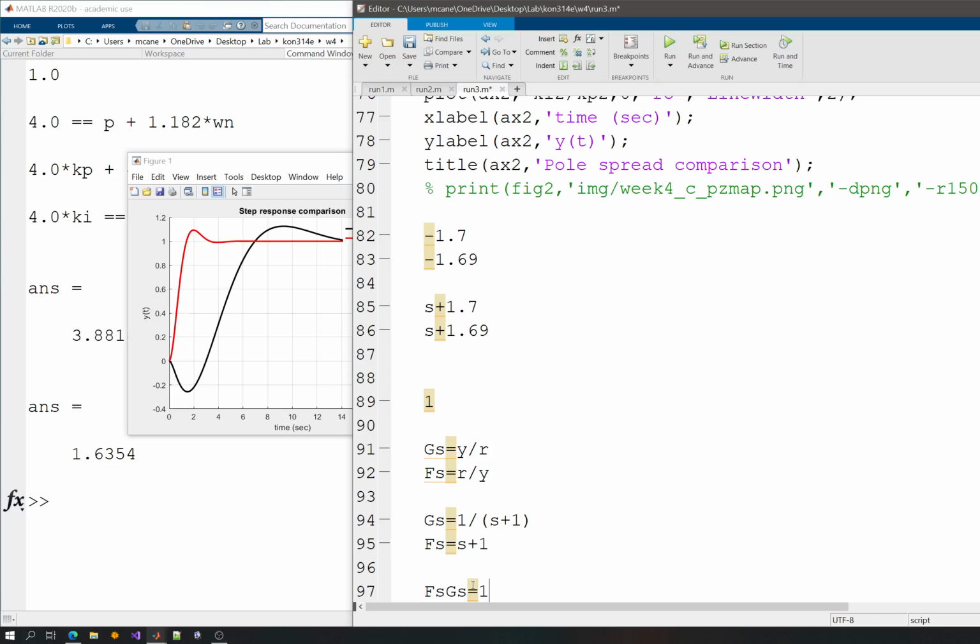Well, if you remember, I talked about an example, a room temperature control system. If I'm using a controller that uses the inverse of the system, then I should have the exact model, first of all. The model should be minimum phase, which means that I should have all poles and zeros of G(s)